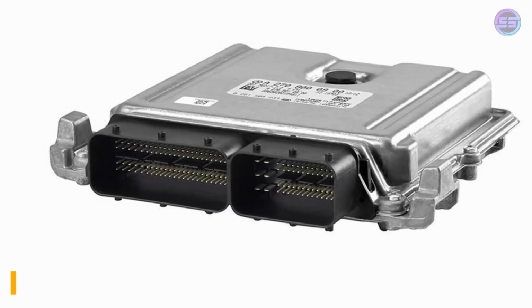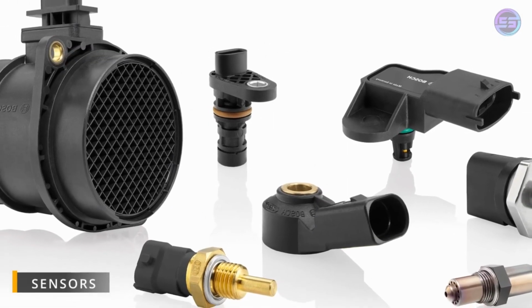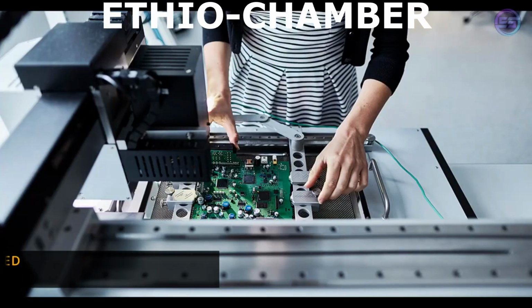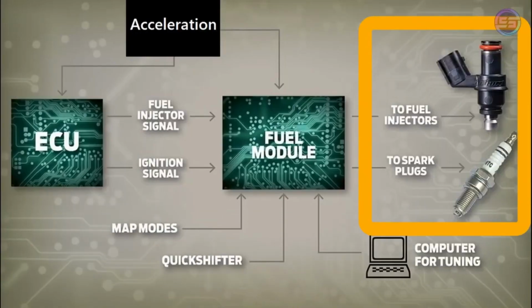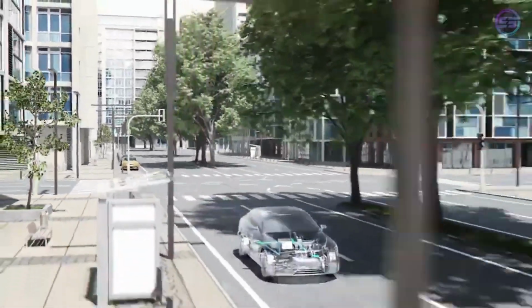The engine control unit, or ECU, receives information from various sensors on the engine, compares that information to predetermined programming decided on by the manufacturer, and then sends outputs to the spark plugs, fuel injectors and other components to allow the engine to run as effectively as possible.